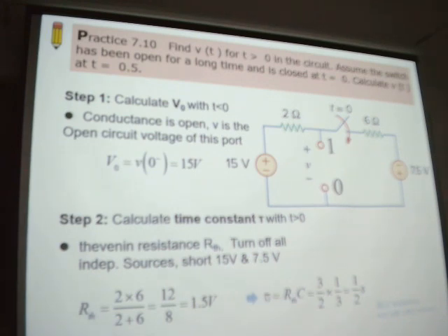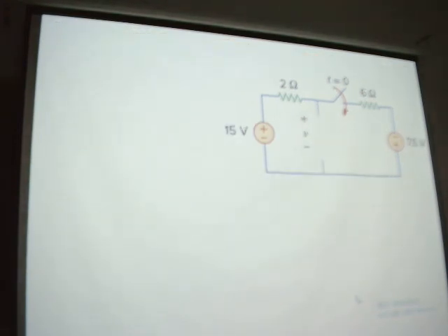And then our tau is always equal to RC for an RC circuit, it's not an RL circuit. Actually, we have RC circuits, RL circuits, and also RLC circuits. But here we just discuss the RC circuit, a first order circuit. Put the value of 1.5 inside, and we get tau equal to 0.5 seconds. And then we go to step 3.